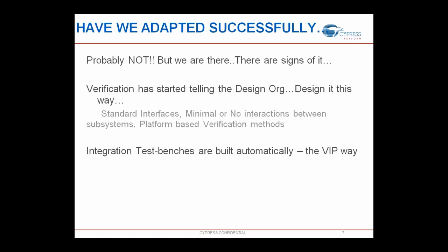I'm going to extend that a little bit. Whenever you build a block level test bench, make the block level test bench reusable. Make sure that you write your SystemVerilog code in such a way that it plugs into any SoC that this block needs to be used in. And associated with the test bench, I also want to emphasize that the test cases that you have should be in the form of APIs and not use hard-coded magic numbers and stuff like that, so that even the sequences and the APIs that you write are completely reusable, built along with the test bench.